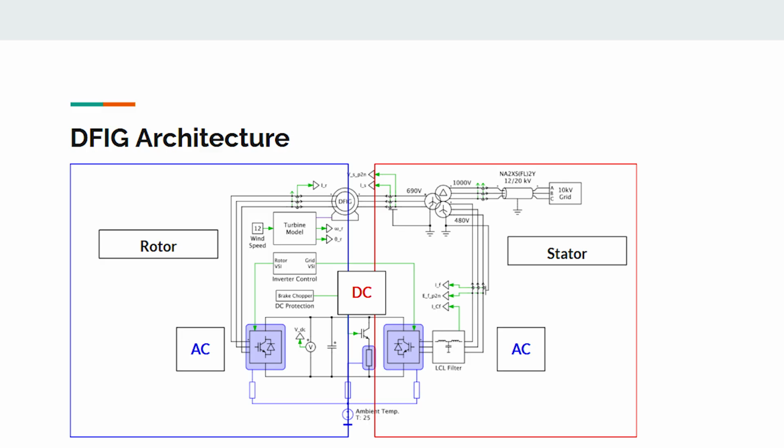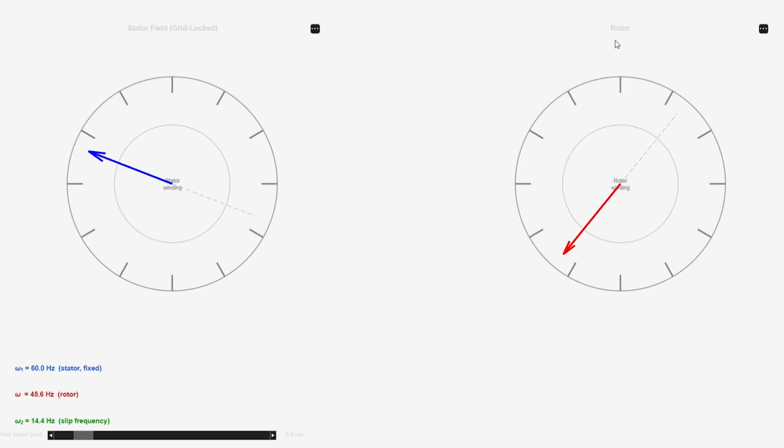A clamping circuit then ensures that enough power is exerted at the rotor to match the frequency of the stator side. The stator side is measuring the reactive and active power along with the frequency of the power as a reference in order for the stator to match for grid hookup. With the simulation shown, the stator speed matches the frequency of the grid being 60 Hz. Depending on the wind speed seen, the rotor will either have to slow down or speed up to match the stator frequency by applying current to the brushes of the rotor, creating additional slip in either direction.